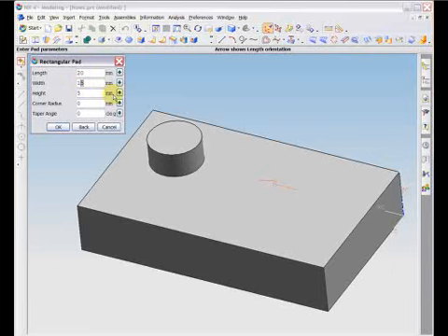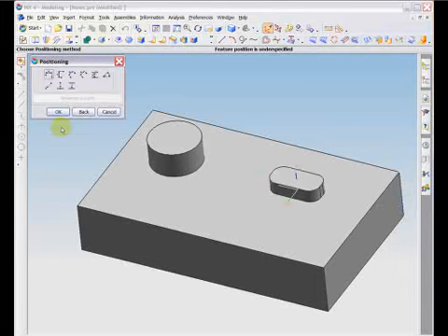You will then need to specify the dimensions for the pad on the placement face. In addition to dimensions for length, width, and height, you can also specify dimensions for taper and corner radius. Corner radius will create edge blends of the specified radius on all 4 vertical edges. Finally, you must again use the positioning options to position the pad.